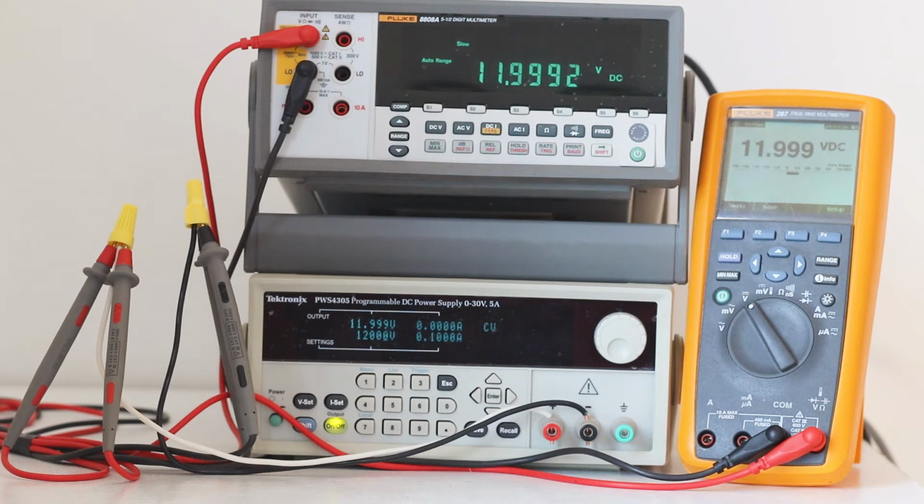Resolution can be expressed in terms of number of decimal places or parts per full-scale reading. Accuracy, in contrast, describes how closely the reading corresponds to an ideal true value. This presupposes either knowledge on our part of the true value or, at the very least, possession of another instrument having greater resolution and accuracy.